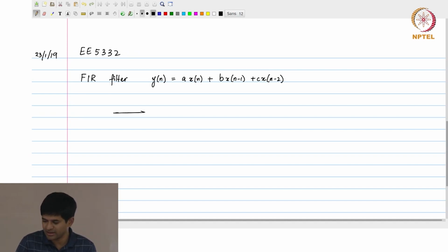It would essentially say, fine, my x of n is coming in here, right, and this arrow over here indicates it is some kind of a multi-bit bus. It could be a 16-bit bus, something like that. All that it means is all of those data are synchronized, they are changing in sync with each other, okay? The shift register essentially says there will be some block which I'm going to just use a rectangle to represent, and at the output of that block is going to be x of n minus 1, right?